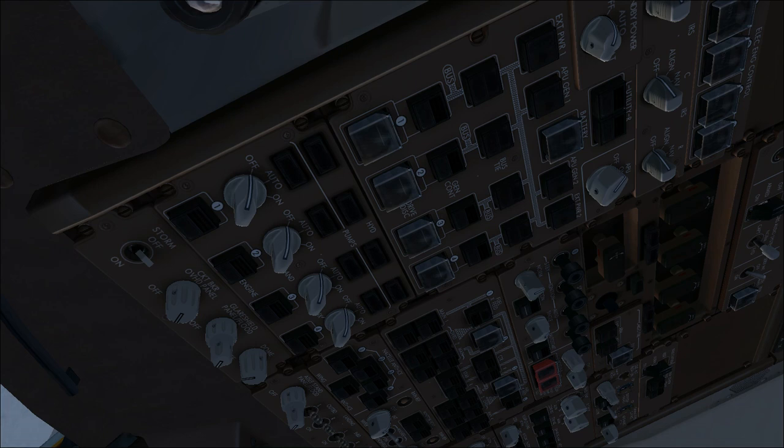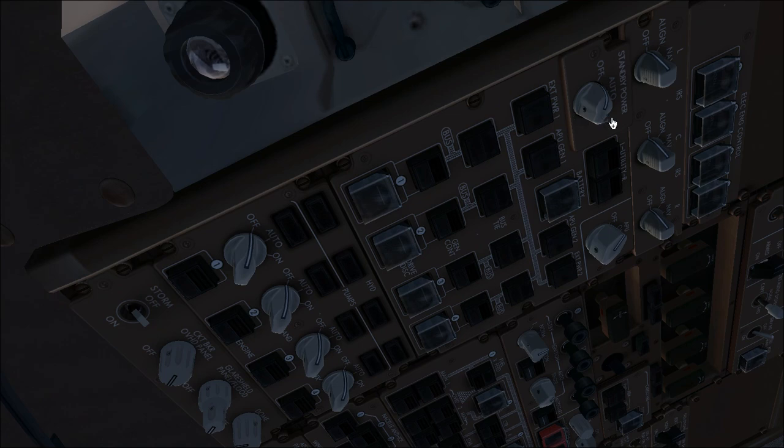Inverters can be powered up by the standby power selector. The standby power selector, when in auto position, senses the DC power output of the battery and opens up the inverters to power up the AC essential buses. If the battery is connected and standby power is also in auto, the DC essential bus will also be powered up, and so we will have some instruments going. With just the battery, you will have the standby instrument and the clock. This is actually the hot bus.